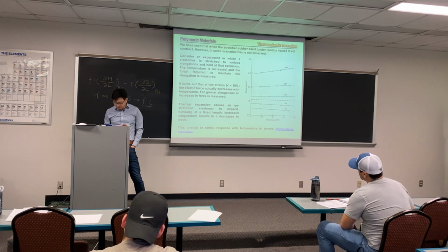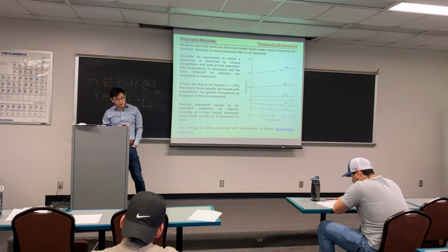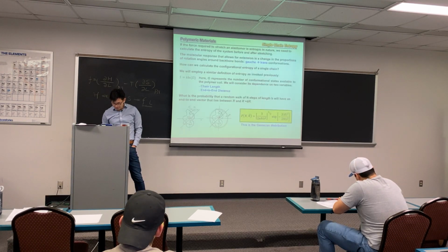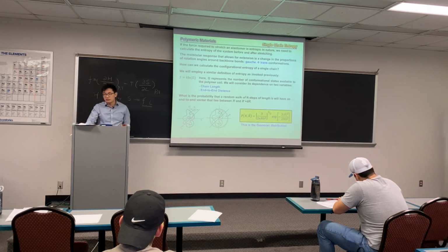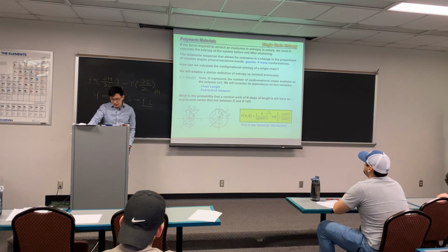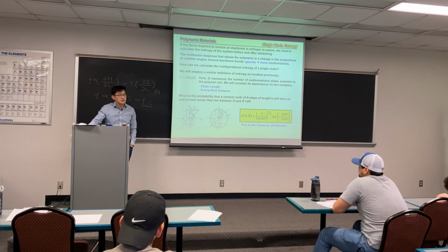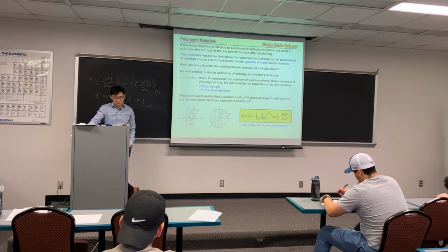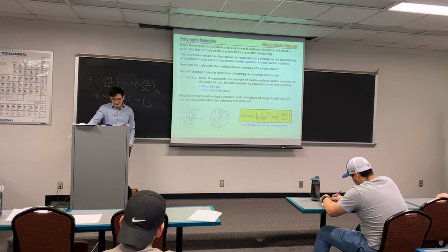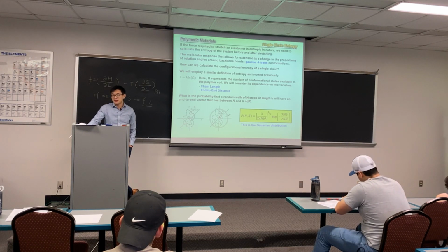So in today's course, we're mostly going to focus on those high degrees of strain, above 3 to 6 percent. That's not the region we should worry too much about. Everybody got this part? Now going back to the concept of entropy. We're going to talk a little bit about single chain entropy. How do we discuss the entropy change before and after stretch? This is kind of a flashback to the first lecture we did.